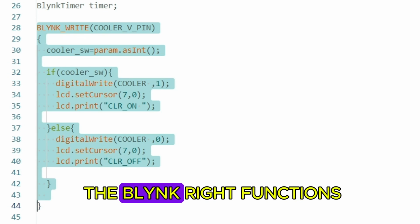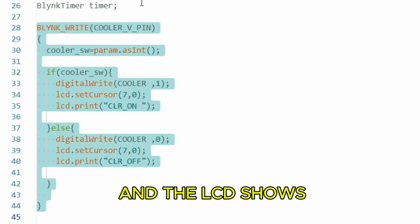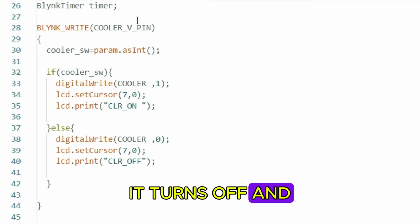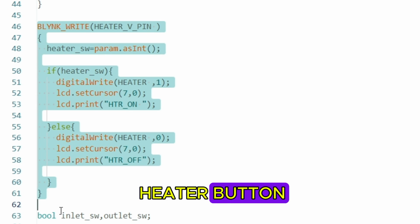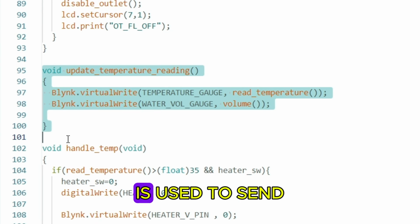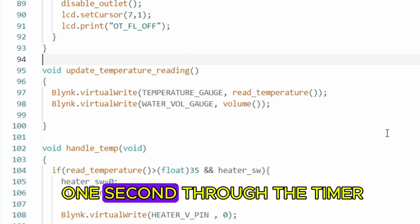Now let's look at the Blynk Write functions. When I press the cooler button on the app, the cooler turns on and the LCD shows cooler on. If I press again, it turns off, and the LCD shows cooler off. The same happens for the heater. When I press the heater button, it turns on, and the LCD displays heater on. The function update temperature reading is used to send temperature and water level data to the Blynk app. This function runs every 1 second through the timer.